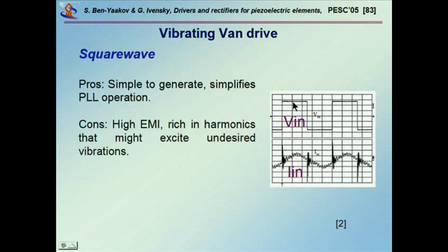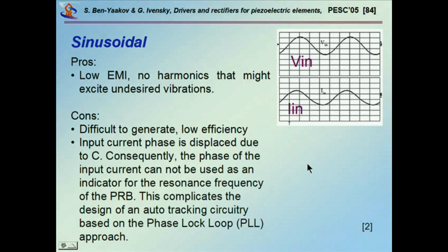Now we have examined various possibilities. One is to use a simple square wave for this type of devices. The problem is that the current is extremely noisy, because you generate these high frequency components, and you have this hard switching at each time, and this would be a very difficult signal for phase locking if you'd like to track the signal. Sinusoidal is the best thing.